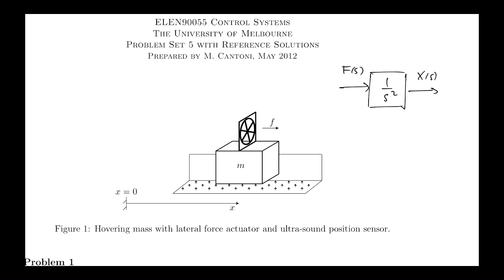And the text there suggests that there will be a difference between what can be commanded and the actual force imparted, and that might be due to a mismatch between the relationship that tells you how fast you have to spin the propeller to get a particular force. So there's some error there, some uncertainty, and we're modelling that uncertainty as an additive perturbation between the force actually experienced by the mass and a command that will be set by the controller.